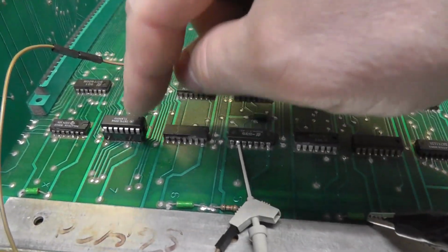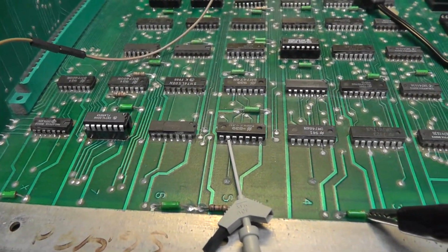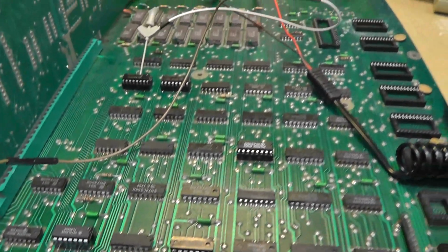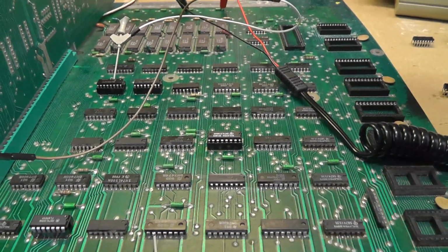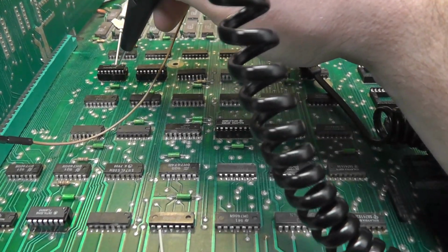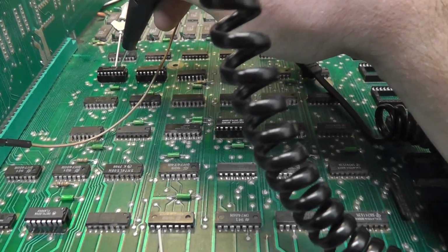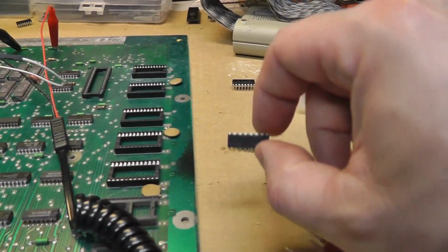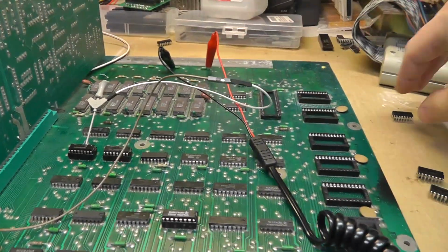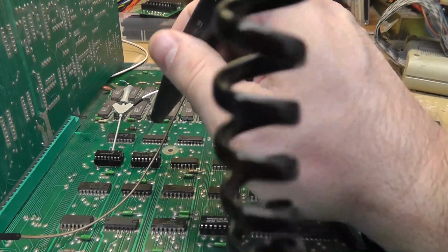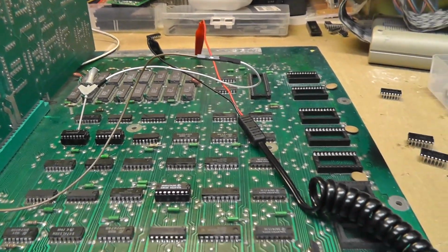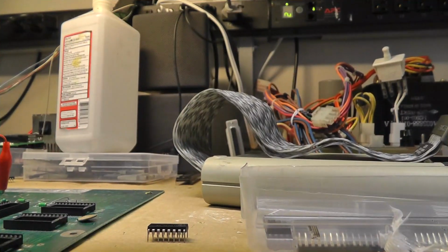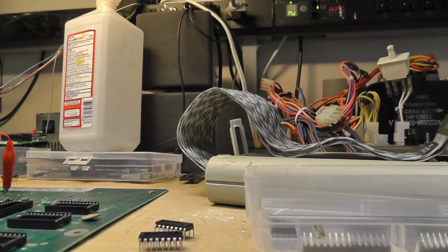Alright, I replaced this, did a decent job pulling it out, and let's see here, but then I still wasn't getting anything, so I was using my logic probe, and the output pins, pin 15 was still dead. It was like floating or something. It wasn't activating. So I was like, all right, maybe I have a bad 74161 here. So I swapped out both of those, and I got some better results. I know it's kind of difficult to see, but there. Could just get it on the tripod, I know.